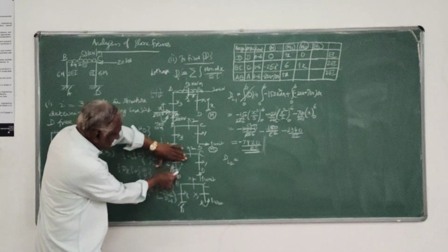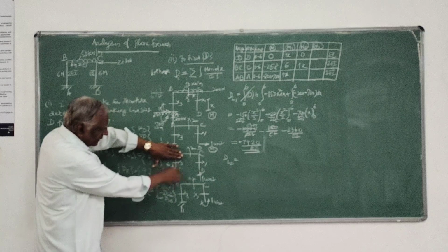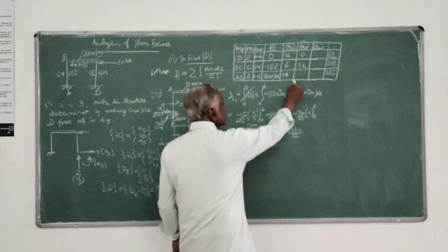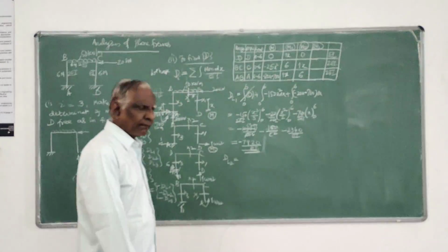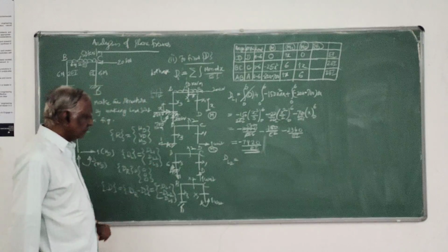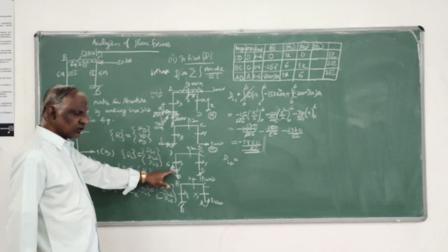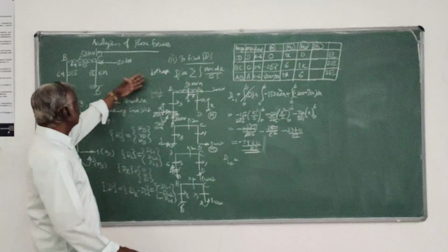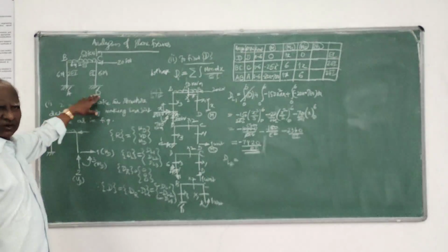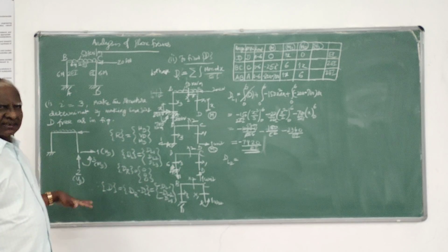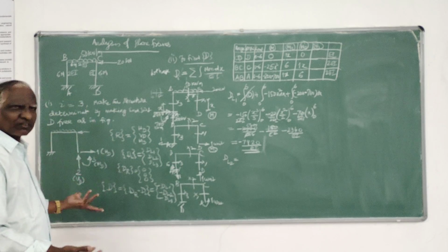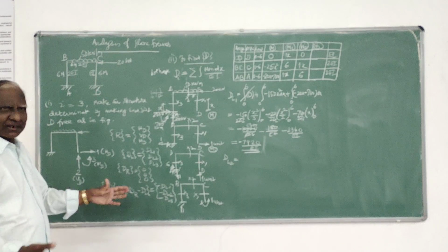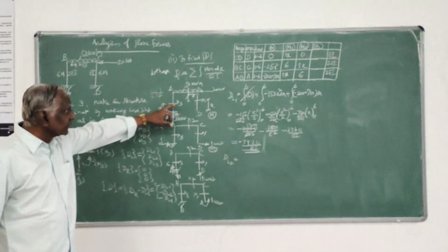Now when you come to this, 6 is there, and this will not give any moment, so it is just 6. So for that section, we don't consider that particular right side 1 unit vertical load, which is at point D. For that section, if you make this determinate by making hinge and roller, you have to take the usual procedure. There also you have to find the reaction, whatever is coming, that you take. That's the fundamental procedure of evaluating, because this is a determinate structure.